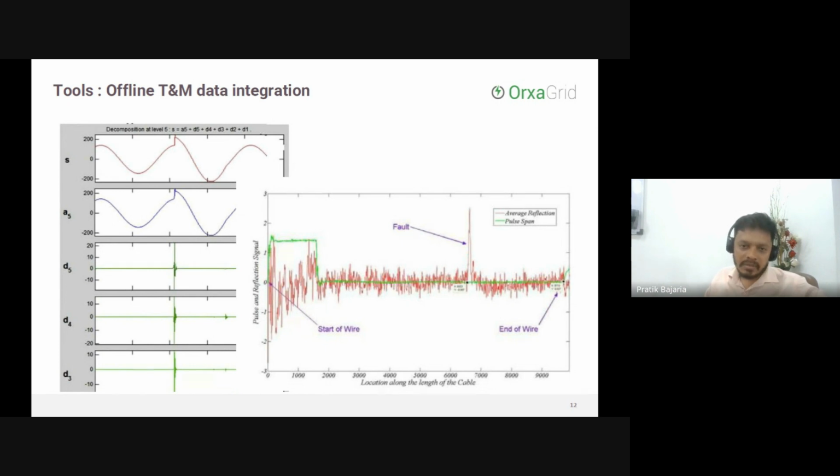If it has occurred, the possibility of a similar set of faults happening in the vicinity is high. Hence, you would try to understand what were the geographical issues that might have caused that fault. One of the easiest and most straightforward ways of implementing this is something called a traveling wave fault locator, or TWFL, where you can insert a surge which gets reflected from the place of fault in the feeder line, in order to understand where exactly the fault is happening.